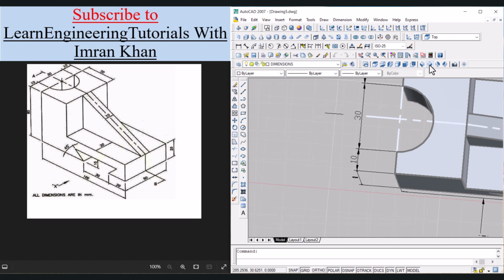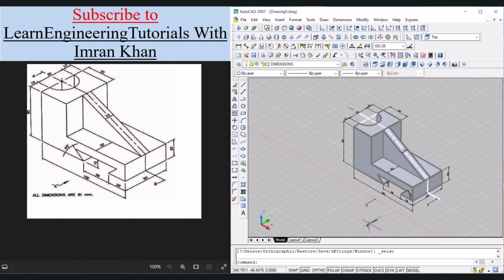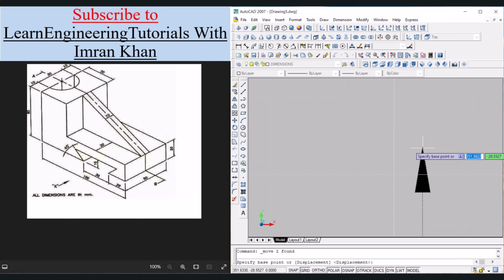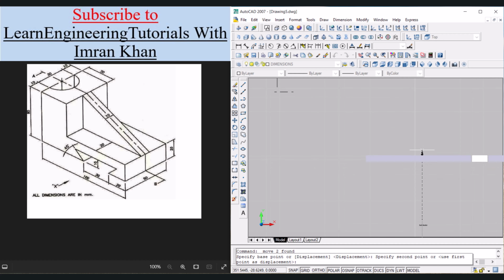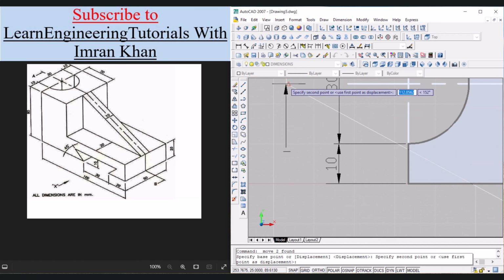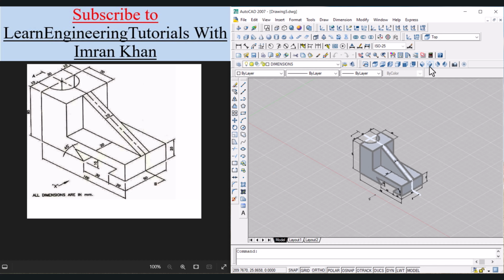Now if you click on isometric view, we will visualize that those two lines were actually A. So select them, click on top view now. This means that this is the text that we want to bring it over to this point. So click on move, select this to be the base point, and then click them and then bring them over to this line. Now visualize them in the isometric view.